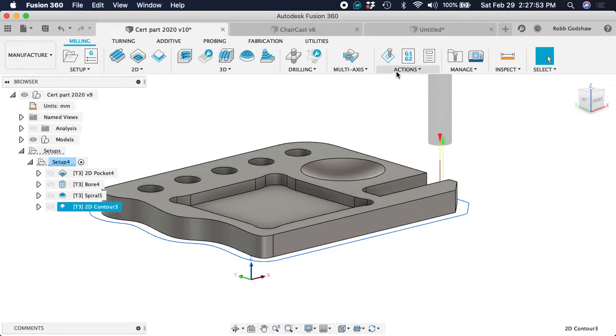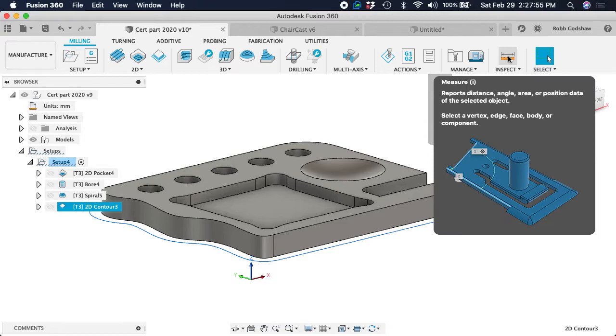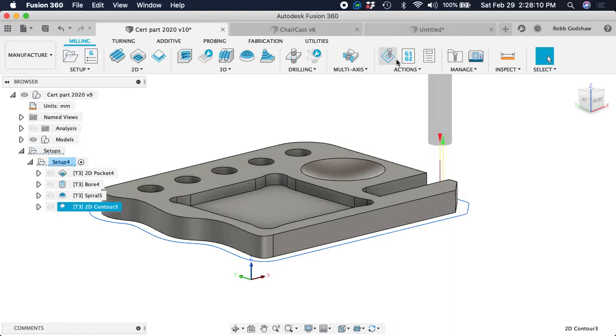So this is 1/2 inch material. If we were going with 3/4 inch material, we'd probably have to cut in 2 steps because you can't go much deeper than the thickness of the bit. So for 1/2 inch bit, you can go to 1/2 inch material, but for 3/4 inch material, it's really pushing it to do it in one pass.